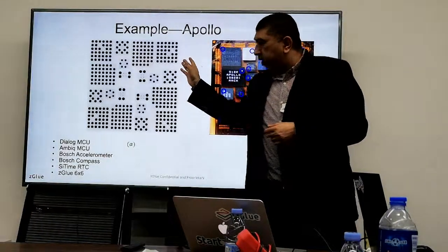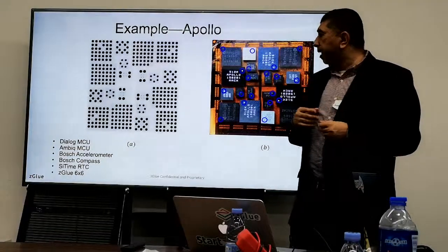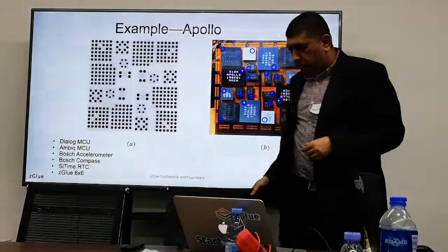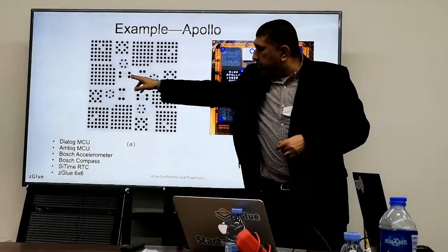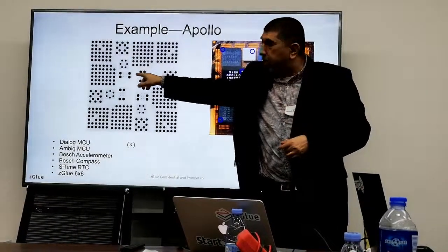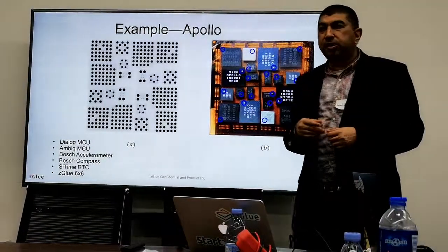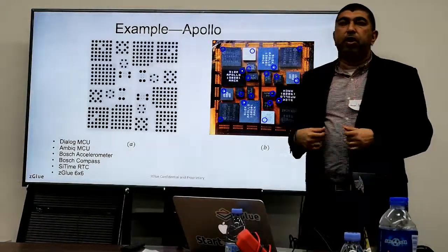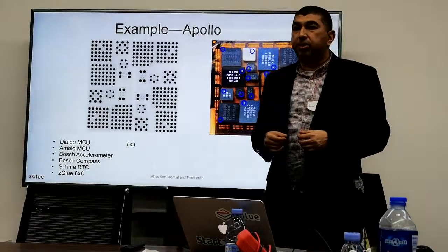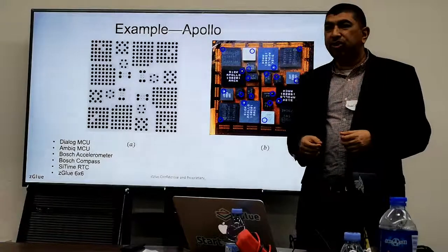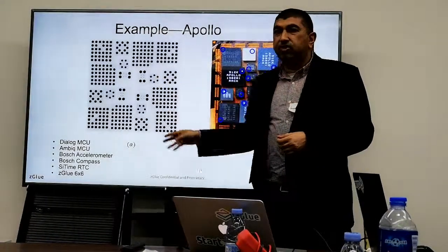So here is the technique that we have come up with. If you pay attention to this picture here, you will see that there are big circles, and then there are really small dots. There are lots of those dots. Each one of those dots is what we call a copper microbump. So those are at 100 micron pitch, and there is active circuitry underneath.